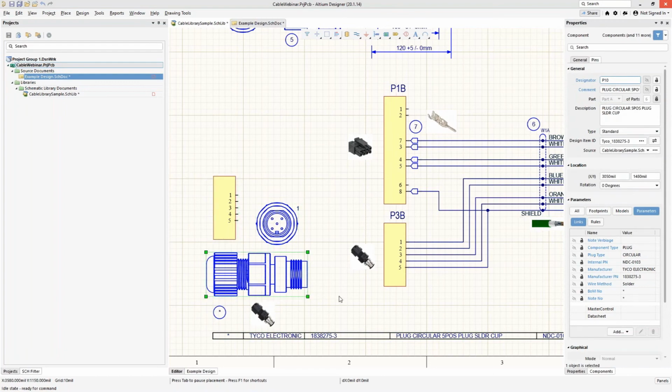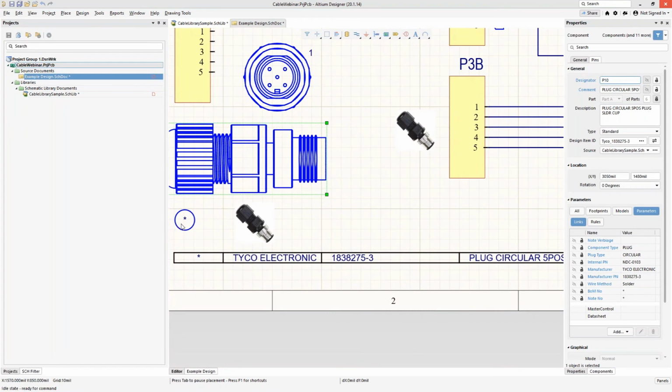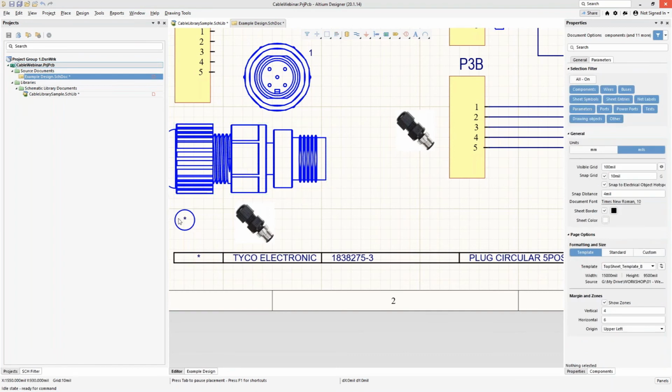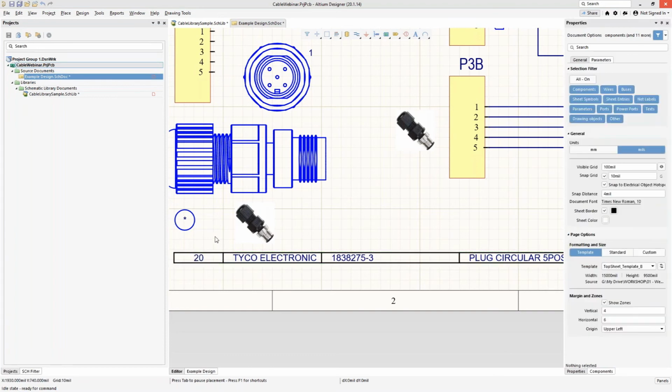Now another thing, because what you just saw is that everything's independent of each other, I do need to fill in the BOM item number here, and I need this here as well. So let's just call this BOM number 20. If I click in this and hit return, or click off of it, that was BOM 20, but notice how it did not immediately put that into the callout or into the line item. So even if I put in the line item here, BOM number 20, and I click off of it, there it is. But it didn't get picked up by the callout.